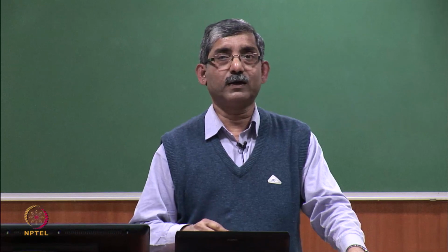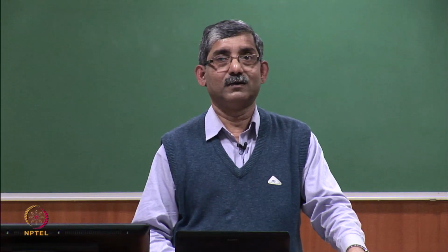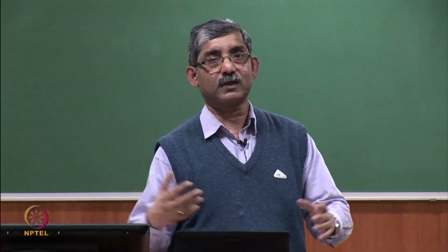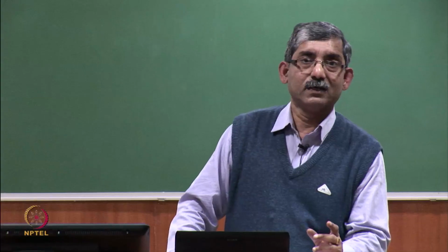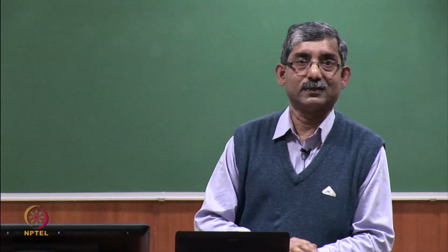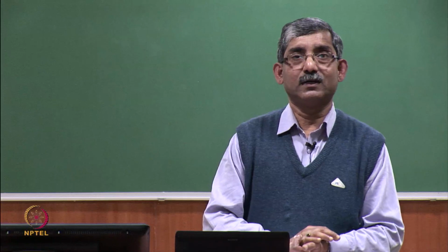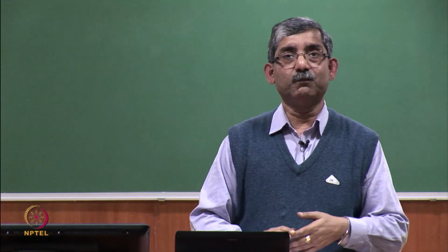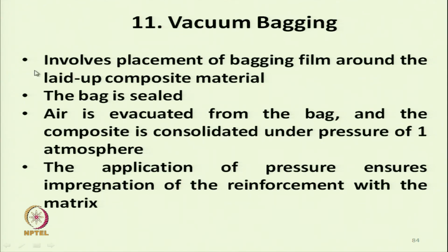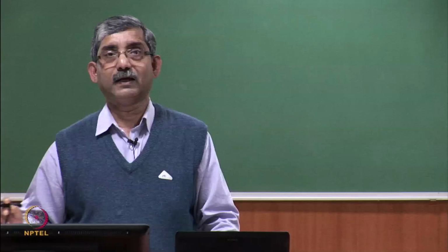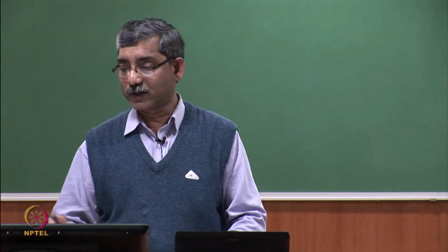Instead, we create vacuum, so that with the help of atmospheric pressure, the impregnation and the compaction take place. Here impervious bags are placed, so that the films are laid on the composite material and the air is evacuated.